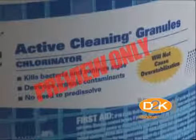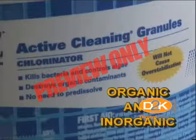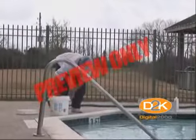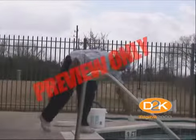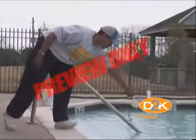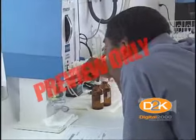There are two main types of chlorinating agents. Organic and inorganic chlorinating agents are not compatible with each other. Many incidents occur when the same scoop or pail is used for both chemicals without cleaning them, or when adding one product after the other, or in the pool chlorinator. Learn the difference between organic and inorganic chemicals.